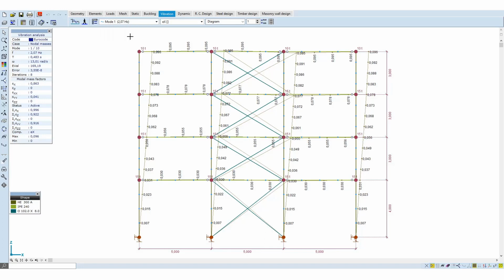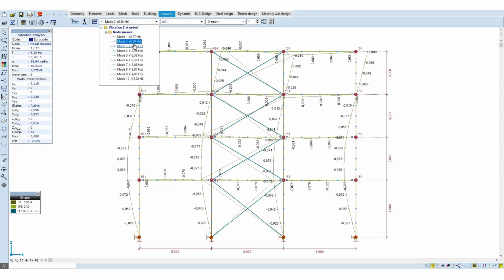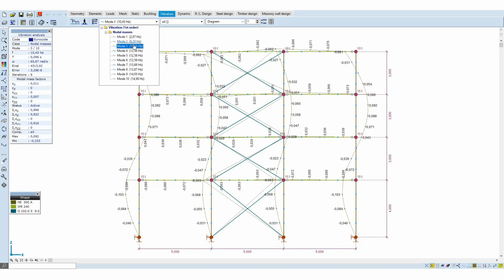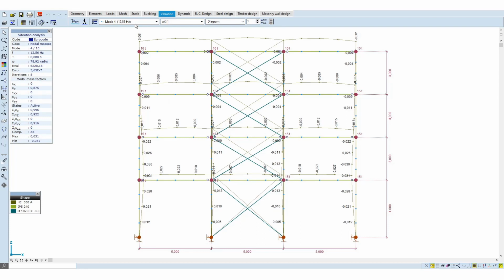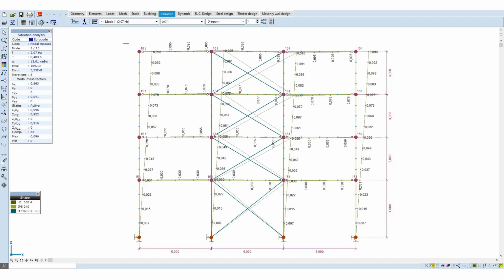The first mode shape characterizes the horizontal vibration with a high modal mass factor, showing that this is the first dominant mode shape to consider. The first mode shape has 2 Hz, while the excitation frequency is 3 Hz, so the structure is undertuned, and during the start and stop phase the excitation frequency will reach the natural frequency of the structure, therefore it will cause a temporary resonance. If we check the tabulated results, we can get the range of interest for the Rayleigh damping coefficients.